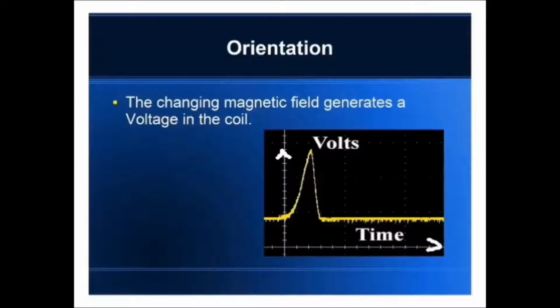So we're going to be using an oscilloscope which connects to the trigger coil output and produces this graph for us. One might think that the output pulse from the trigger coil just looks like a positive pulse. The voltage is along at zero, the magnet comes by, and bingo, we got a positive voltage which goes to the control module to fire the spark.